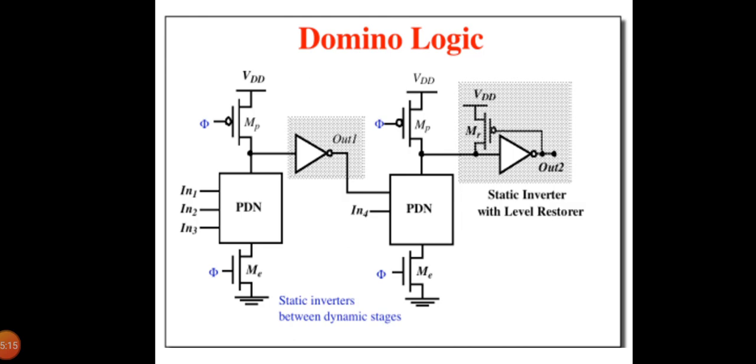A major limitation of domino logic is that only non-inverting logic can be implemented, and this requirement has limited the widespread use of the pure domino logic. There are several ways to deal with it. One approach to the problem is recognizing the logic using simple Boolean transforms such as De Morgan's law. Unfortunately, this sort of optimization is not always possible, and more general schemes have to be used.